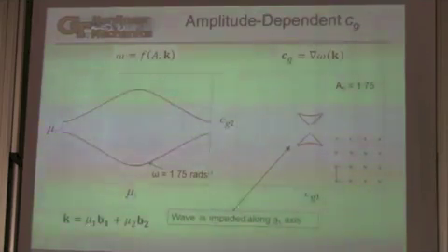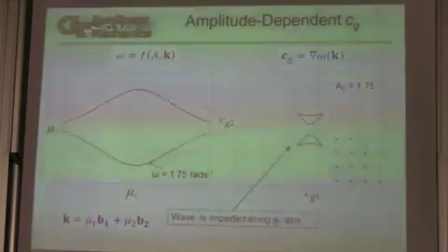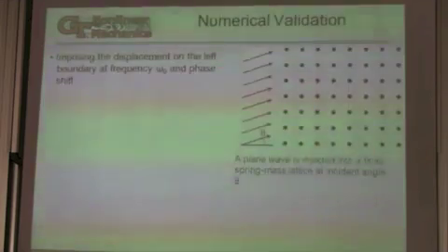Now we do not have a wave that can propagate with simply an X component of group velocity. We don't have any dispersion on this line. We have to jump up to Y. That means the lattice won't support, at this amplitude, waves that are going to propagate strictly in the X. And that's what our perturbation approaches are telling us. So again, we can go and simulate. As I said, we try to learn from the perturbation approaches.